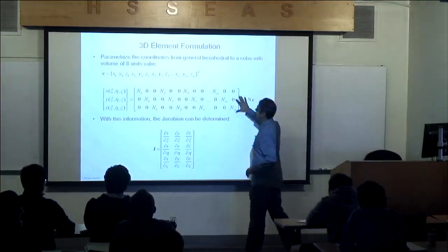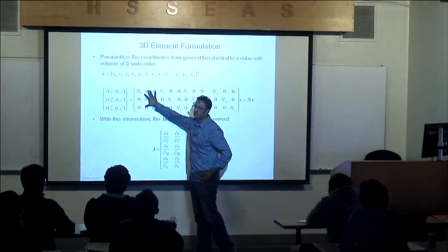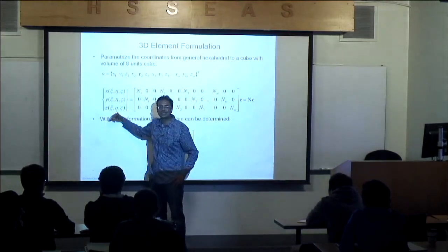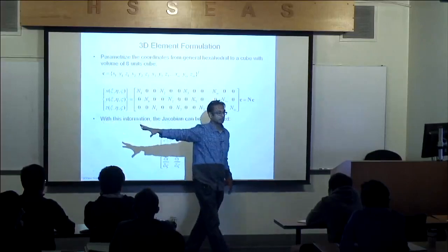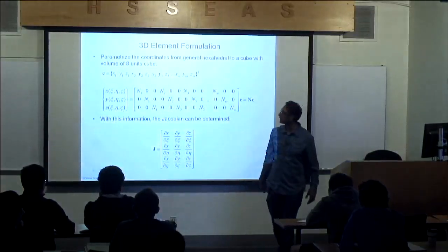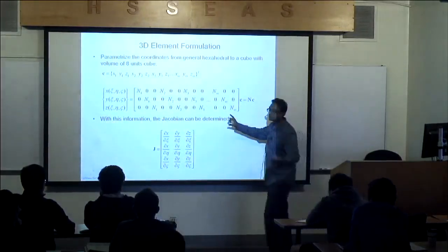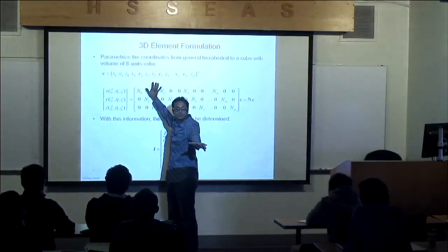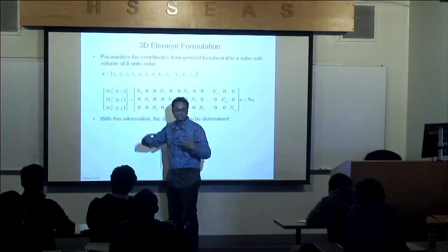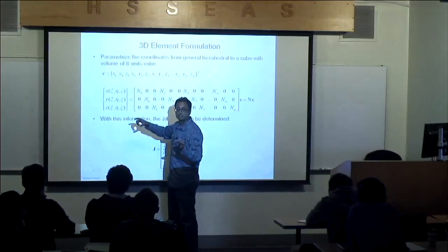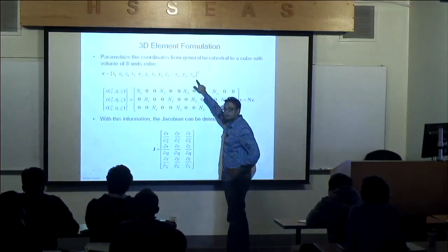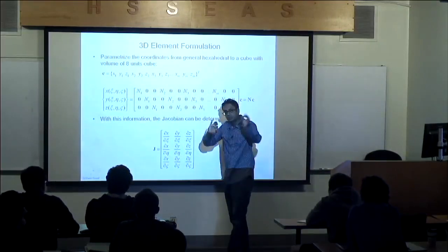So the idea is that if I multiply the shape function matrix times its coordinates, I recover the locations in the global system, x, y, z, right? And then you agree that I know the coordinates of every node in a particular element? Yes, you know it because you constructed the model. And so the software knows these numbers altogether. It knows it. Okay? I know the nodal locations.